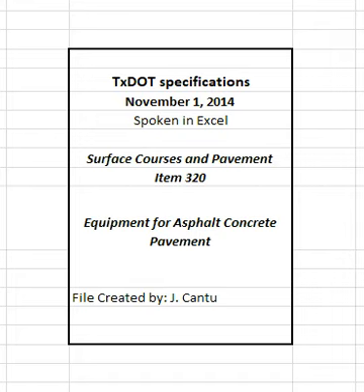Synchronize equipment to produce a mixture meeting the required proportions. 2.1 Production equipment. Provide drum mix type, weigh batch, or modified weigh batch mixing plants that ensure a uniform, continuous production. Automatic proportioning and measuring devices with interlock cut-off circuits that stop operations if the control system malfunctions. Visible readouts indicating the weight or volume of asphalt and aggregate proportions.